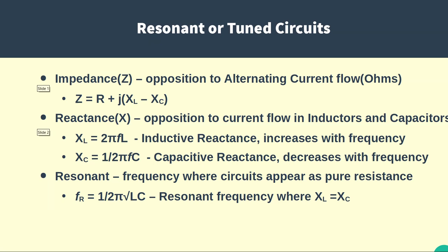And if you multiply that out for a given frequency, you'll find out what the reactance is in ohms. And we normally represent inductive reactance as a positive value. So if you plot it on Cartesian coordinates, you'll plot resistance on the horizontal axis, and you'll plot inductive reactance on the positive going vertical axis.